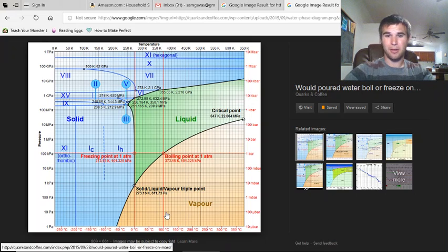I also think, just doing it manually, you could literally just have a dial that you set pressure, and then have another dial that you set temperature, and those controls are incredibly cheap to purchase for refrigeration equipment, where it literally just says, over that set point, turn the air conditioner on.